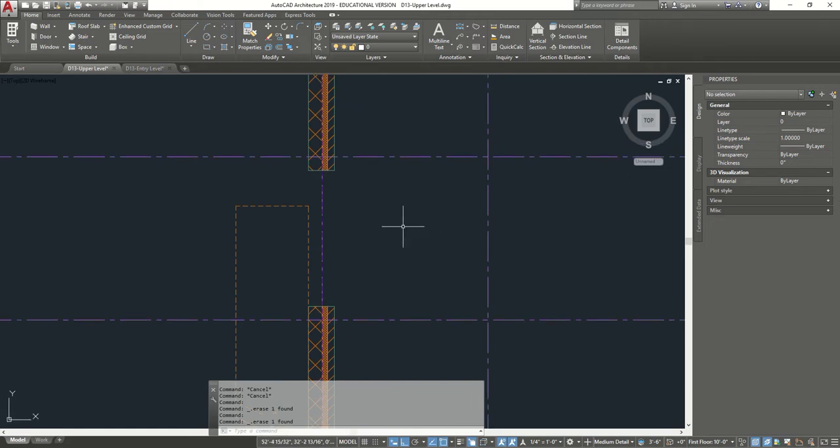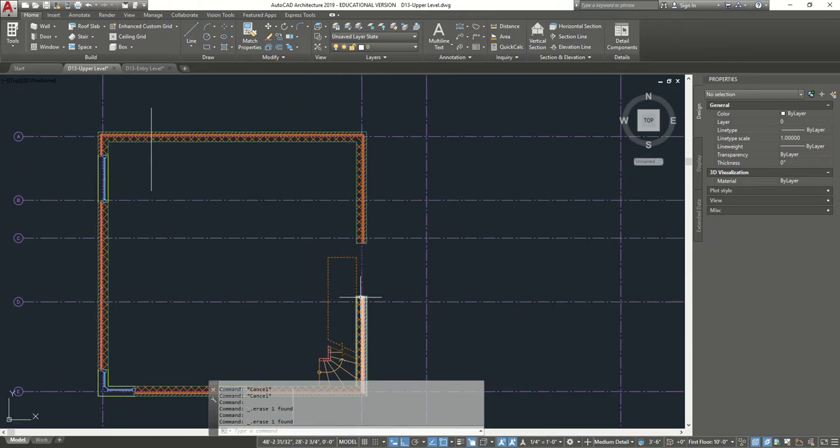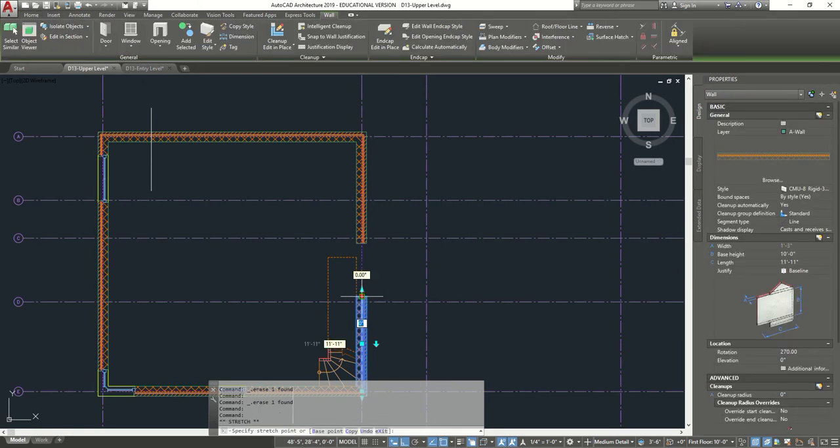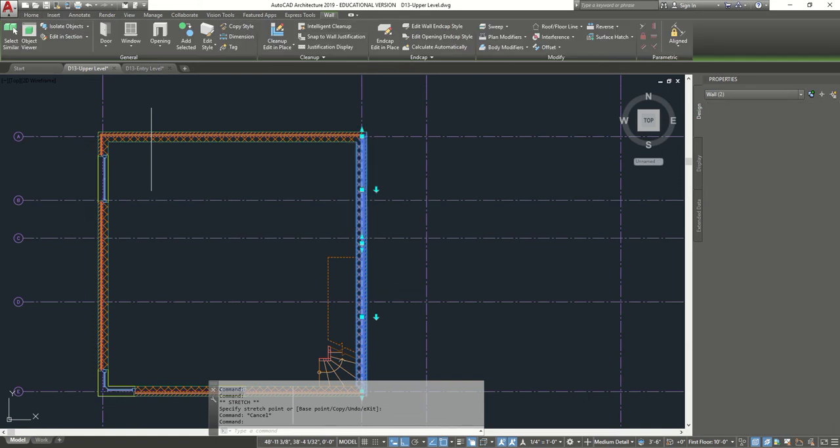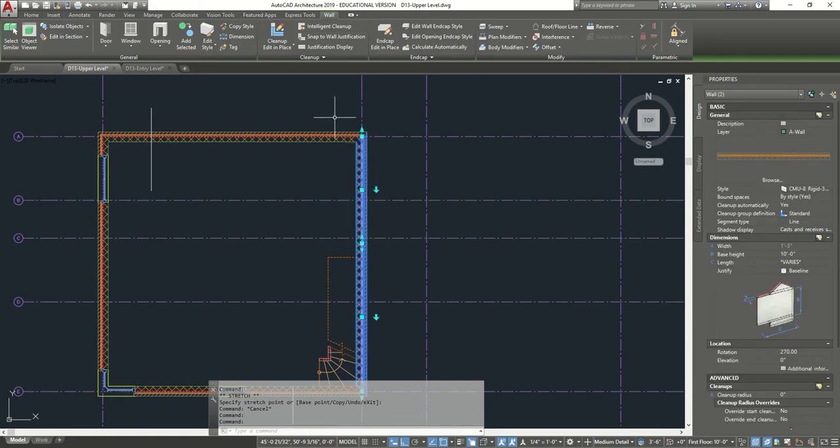Now for the hole here, we have two options. We could just drag it up like so, and drag it to connect it. You don't have to. We could also have deleted the wall altogether and used fillet, or since we did two walls, just click on both walls and use the join option, which should be found under cleanup. Join the walls.